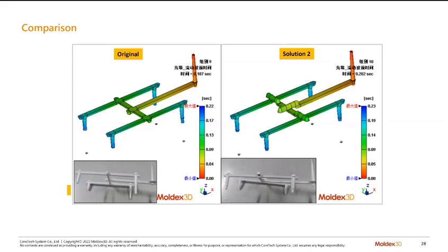Okay, here's the next one. Why not go for a hot runner system instead of a three-plate mold? For this one, actually, the mold is chosen by the customers, and I think they have some budget issues, so they chose the three-plate mold. The hot runner usually costs more.